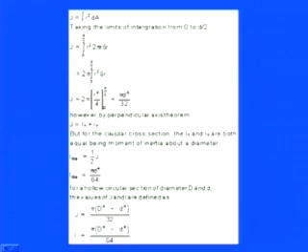So we can say that J is equal to Ix plus Iy, because in the previous section we found that when all three axes exist together, they have the relation Ix plus Iy is equal to J. Since it is a symmetrical section, Ix and Iy must both be equal to the moment of inertia about this particular diameter, because we are concerned with a symmetrical geometry. So Ix and Iy have equal value, and I diameter is equal to J by 2.